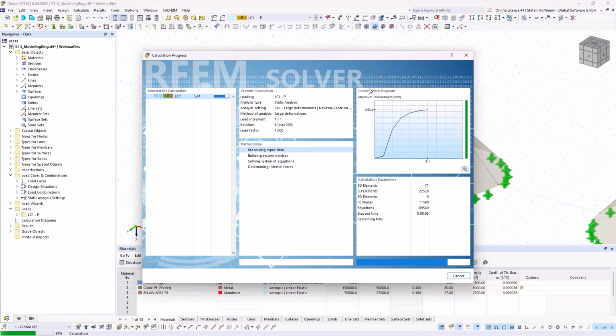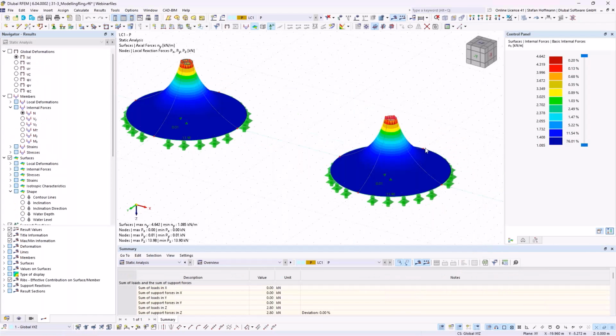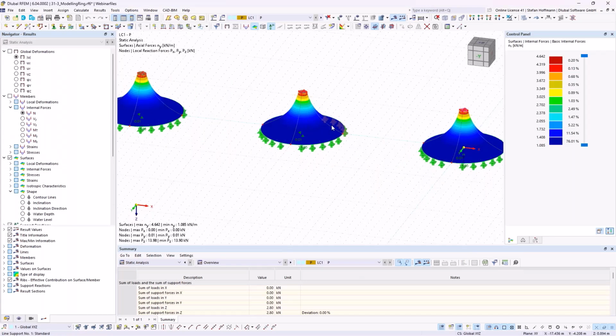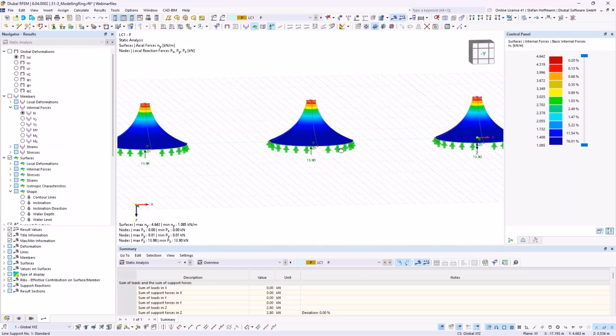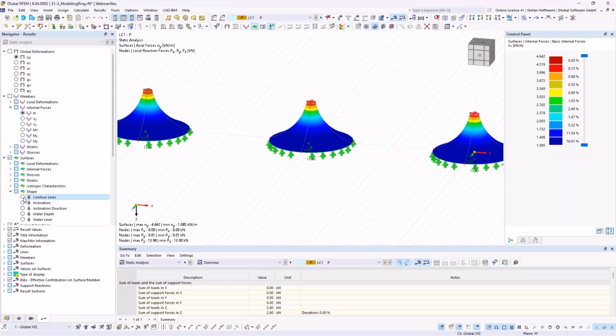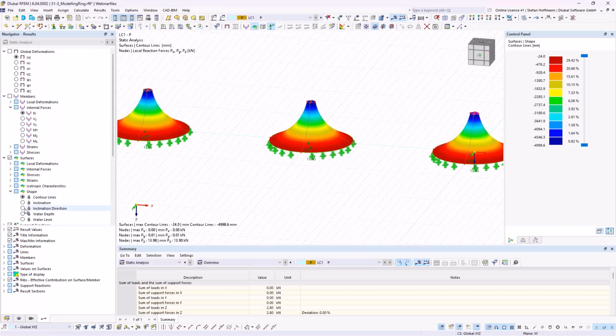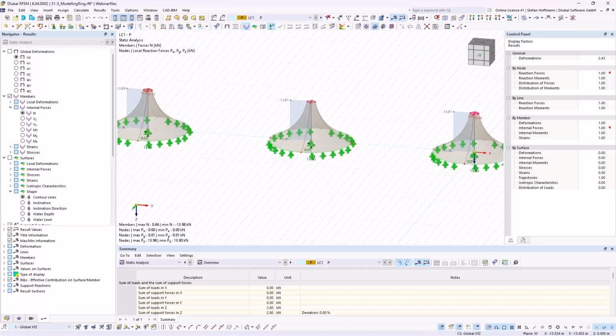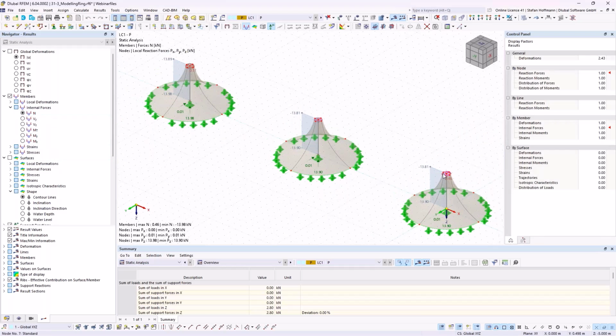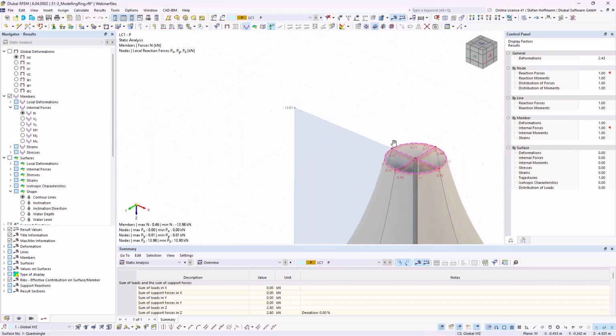Sometimes you need temporary supports, depending on the numerical stability of your file. For this, we don't need them. We can see that the deformation should be similar, and also the inner forces. But then the member forces can, of course, differ from our rigid connection and over here.